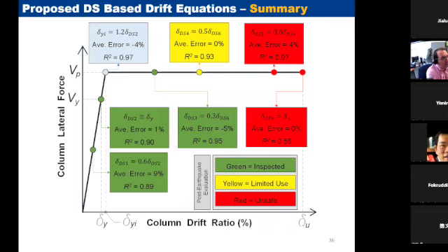We also know that damage state 3 is no more than 30% of damage state 6, which is the failure of the column. So if your inspector is reporting damage state 1, 2, 3, that column could not see, statistically speaking, any displacement more than 30% of the failure displacement. So you have 70% reserve capacity.